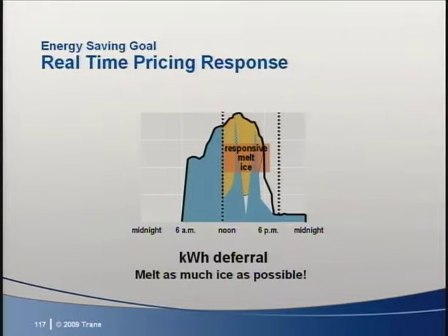It could, however, involve a sophisticated, internet-based real-time utility rate monitoring application. Real-time pricing could really make an ICE energy storage system dance. By this, I mean it will want to control the system to be real-time price responsive. With real-time pricing, the electrical utility can change the price they charge for electricity as often as every 15 minutes. The good news is that they give the building a 15-minute warning of a pending change in price. Based on that warning signal, the control system can easily change from an all-chiller cooling mode to an all-ice cooling mode, or even to a combined cooling and ice-making mode.